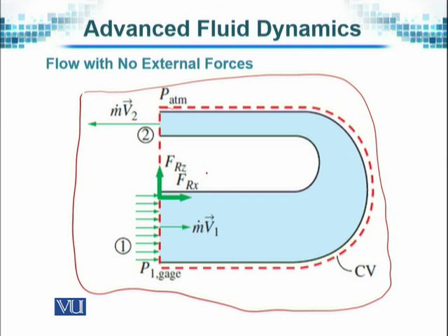The force components are here in the x direction as well as in the z direction, shown through the green thick line. The fluid flow is being moved in this direction, entering here and moving out in the reverse direction, and we have then calculated the force that is needed, which is equivalent to about 260 kilograms.